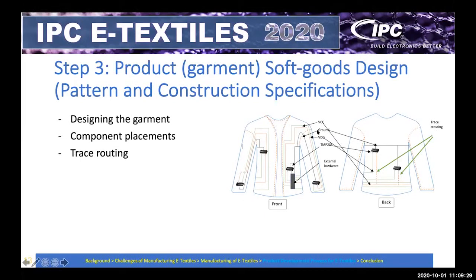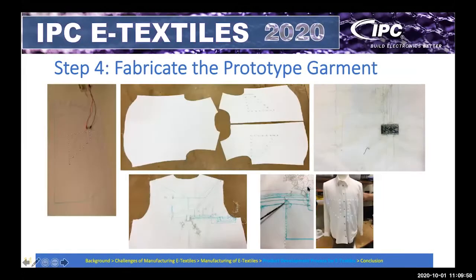And then there are situations where you can see the traces go one over another. Here is an example. So you have to make a plan. You have to ensure that you have a small number of traces, but there will be situations where you'll have trace crossing and seam crossing, and you need to use the proper technique to do the trace crossing and seam crossing in e-textile. And I already described some of the techniques in my previous slide.